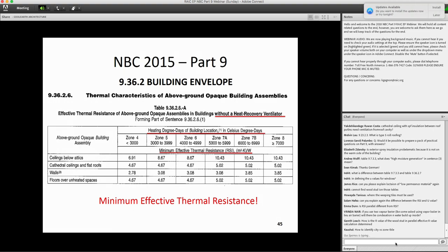Determine when to use damp proofing and waterproofing. You can use damp proofing below grade when you show that there is no water table close or near to the footings of the foundation. It is certainly cheaper and easier to do damp proofing only, but if there is a water table nearby or hydrostatic pressure that might be happening in the wall assembly, you need to use waterproofing.